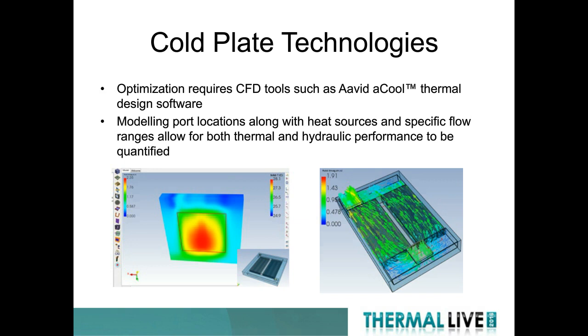When we're developing the full fluid network, we can't just assume that this is going to be fixed flow. The flow is very pressure dependent, and so this is where we're using a lot of the CFD tools to be able to predict the actual fluid flow that you see in the bottom right picture. So you can see the flow fields that are being distributed through this cold plate.